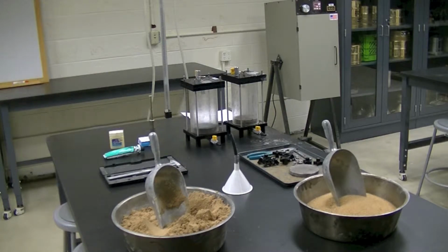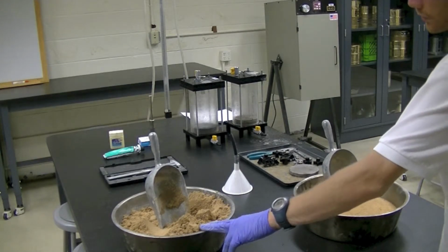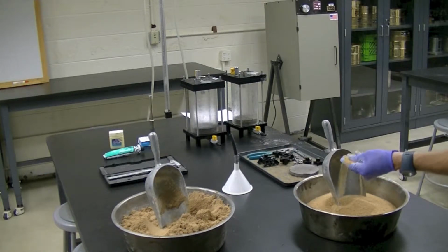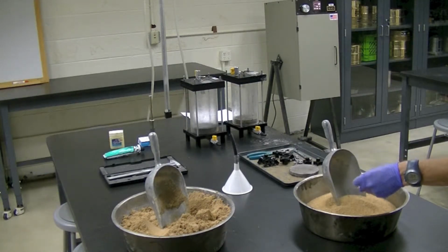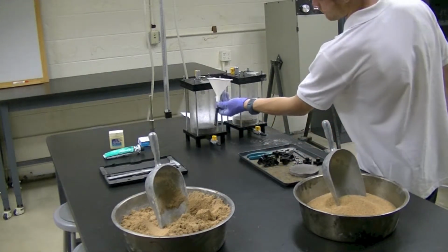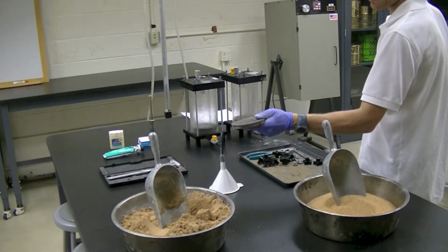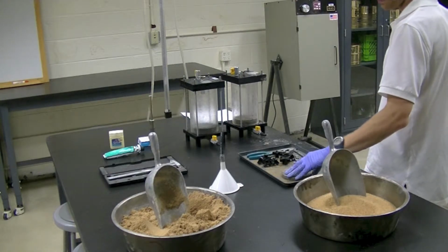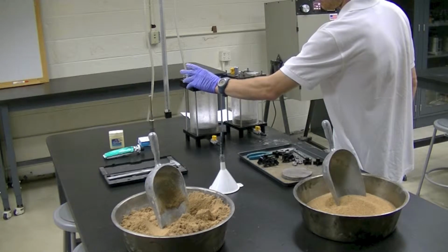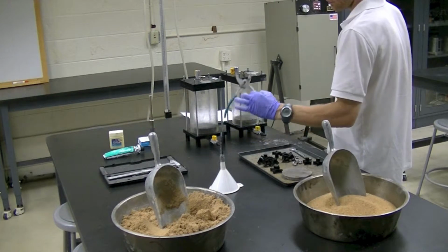We will now introduce the tools used for testing. First we have our fine-grained soil, which is our clay sand. Then we have our coarse-grained soil, which is a fine to medium sand. We have a funnel with a spigot on the end that reaches the whole length of the permeameter. We have a porous stone that fits on either side of the sample. We have our wing nuts to keep the permeameter tight and watertight as well. We have our wrench.